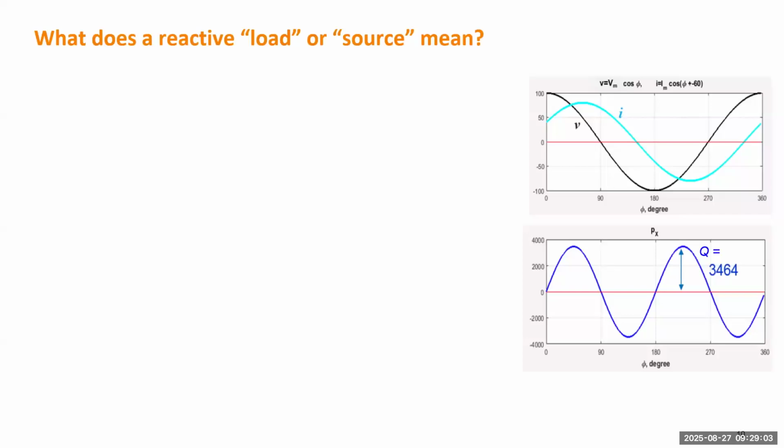And for that example, we know in this case the Q is positive because we treat the load as load, and this Q also as load. So we call this pattern of Q or instantaneous power a reactive load. So the reactive power of a circuit element results in no real energy consumption. If you have a device, for the first item, the P_R is exactly 0, but it only has something like P_S. Which means this device doesn't cause any real energy consumption or contribution. But the Q can be either positive or negative, depending on the pattern of this waveform.